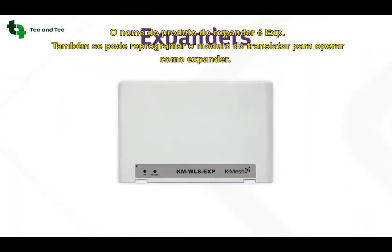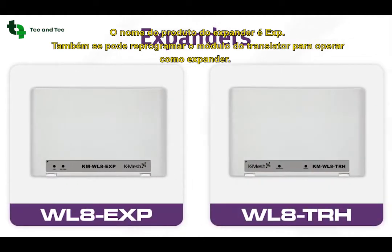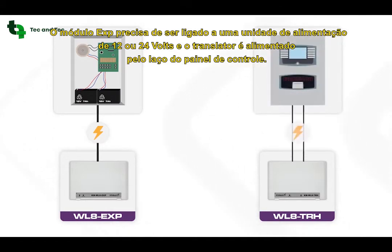The product name of the expander is WL8EXP. You can also reprogram the translator module to operate as an expander. The WL8EXP module needs to be connected to a 12 or 24 volt power supply unit, and the translator is powered by the control panel loop.